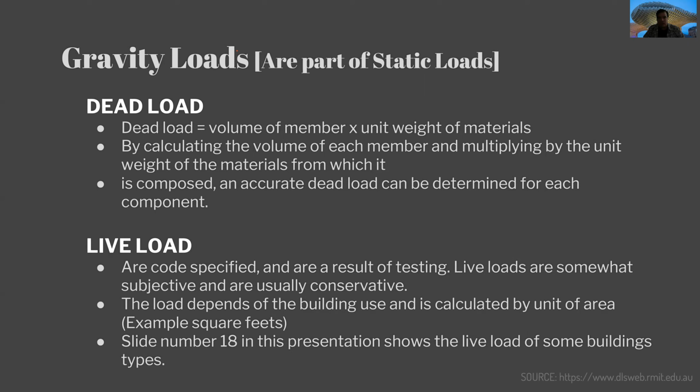It's very accurate because we know the exact dimensions of the materials. And if we have, for example, a wall made out of a specific drywall of a specific dimension, we know, with tables, how much is the weight of this material per volume. It is enough to calculate the volume multiplied by the weight, and we have material number one. And after, we will do the same with every material and every element that is fixed.